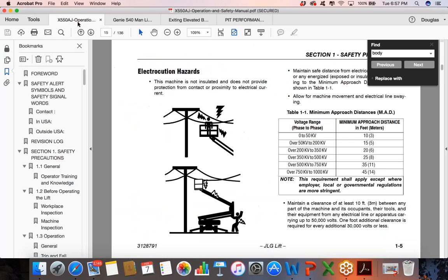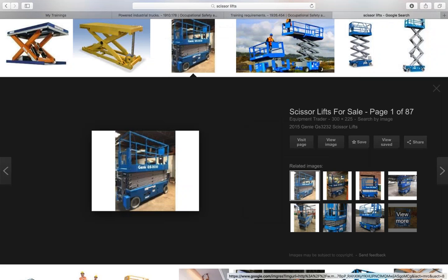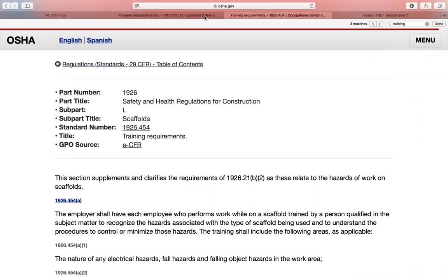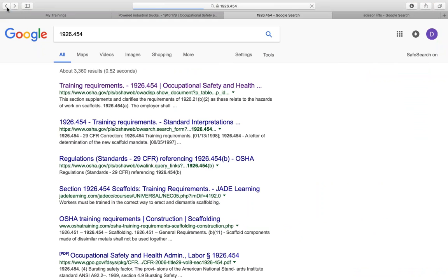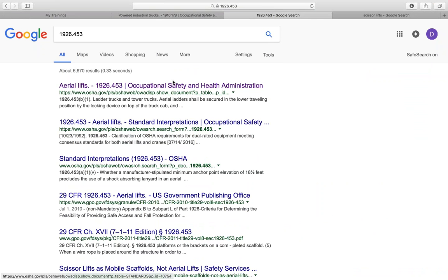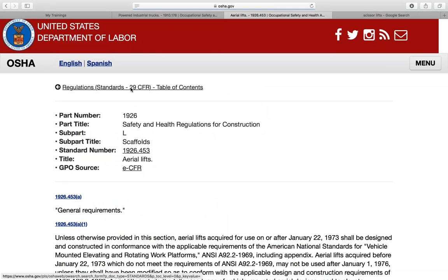So let's start with this. Let's start with the aerial lift for a JLG. Let me ask you, folks, who's aware? Let's start with the OSHA standard. Let me back up one step, okay? Let me ask you, folks, who is aware, and I'm going to go back to 1910.453. Who's aware that the OSHA standard actually allows an employee to wear a body belt in an aerial lift?